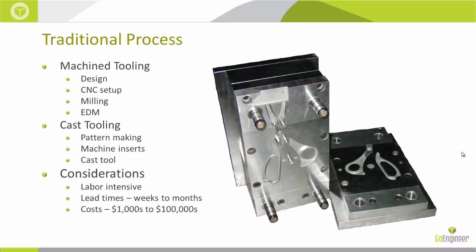If we have very strict requirements for the surface finish, if they're physically large parts, if there's some unique geometry, we're going to find a 5-axis machining center, and we're going to machine it in 5-axis. If we're a little bit unlucky, there's going to be some very small features or some very tight or sharp internal corners, and we're going to have to go and get these EDM, which is even more expensive because there's even more tooling that has to be created for your sinker EDM process. So that's a very time-consuming process that eventually you might have to do, right?